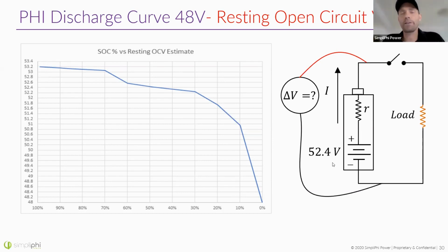Environmental conditions matter. All of these cylindrical cell batteries have a vent in them. They're hermetically sealed, which means they're sealed, but they're inside a steel case, and the vent is there in the case of high temperature, high pressure. When the pressure builds up to about 10 times atmospheric, that vent opens up and they off gas.